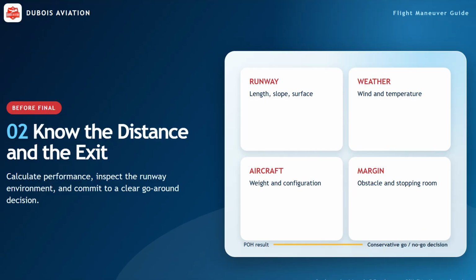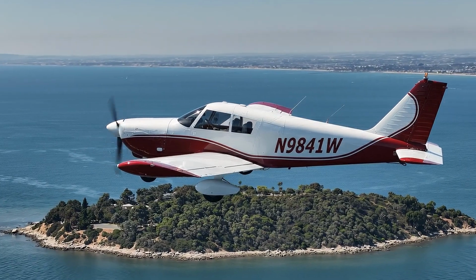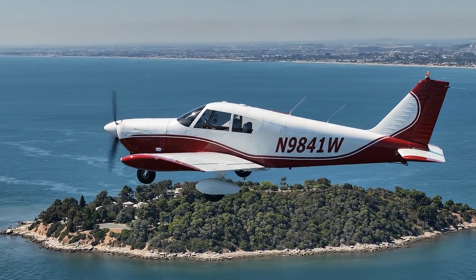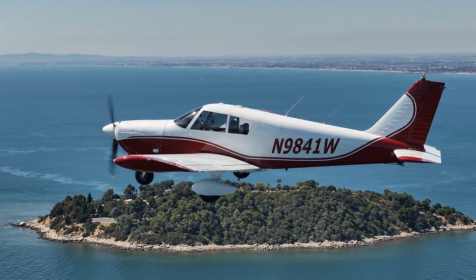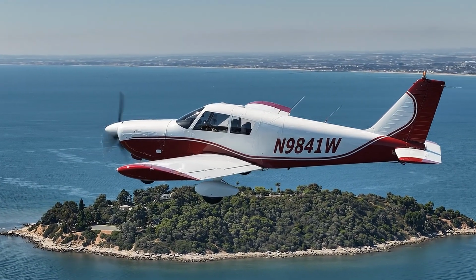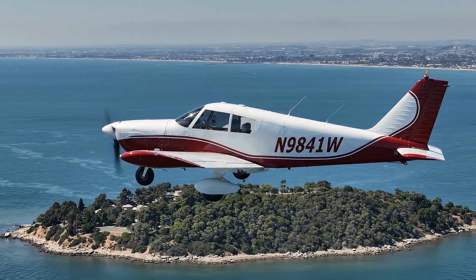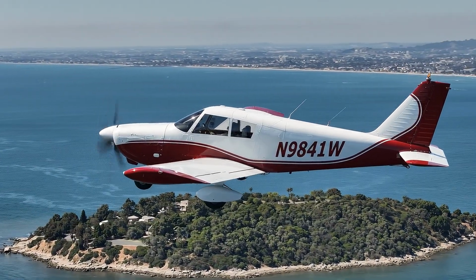Brief the flap setting, manufacturer recommended approach speed, aiming point, touchdown point, and go-around trigger. If the approach is unstable, the obstacle cannot be cleared comfortably, or the touchdown point will be missed, go around. A short runway is the wrong place to salvage a poor approach.